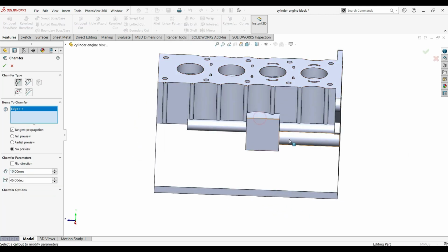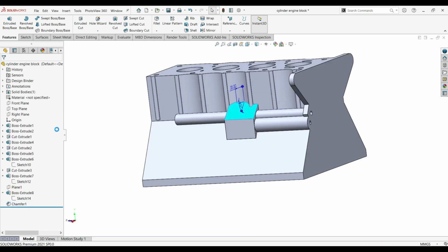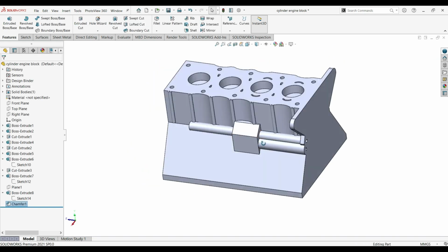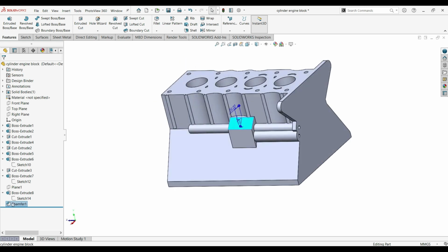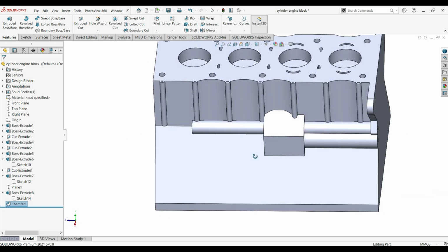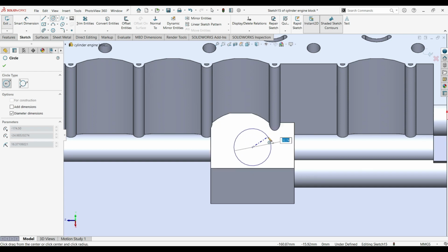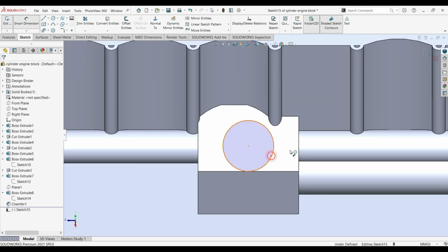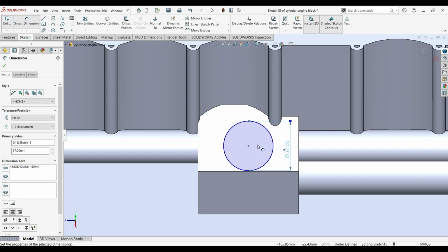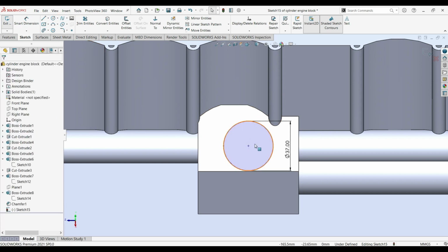Okay, now let's here use the chamfer, and here we'll put 25 and click there with the distance and angle. Okay, maybe 25. Okay, now it is better. Now sketch here. Okay, so it is good. Now I will sketch on this surface, and here we'll make one circle, and we'll touch there, and here 32, 37. Okay, 37, and one more inside.